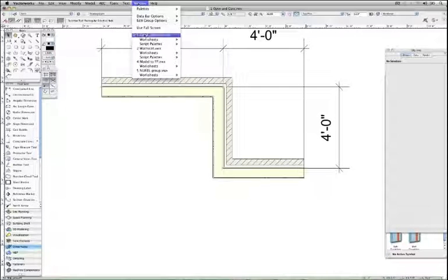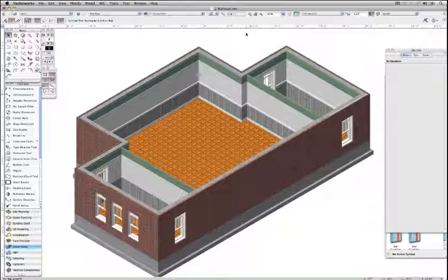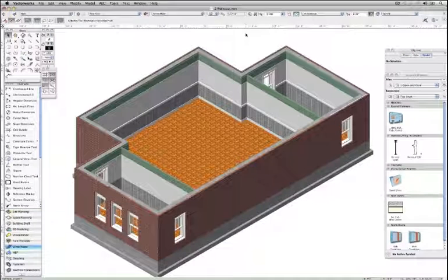So now I'll switch up my files a bit and go to the beginnings of this simple building. This tip involves using the new 3D wall components as wainscoting. In case you haven't seen this, in 2011, wall components are now actual 3D elements. They can and should be classed individually and can take on textures and hatches independent of each other. This brings up all kinds of cool possibilities downstream when looking at sections.